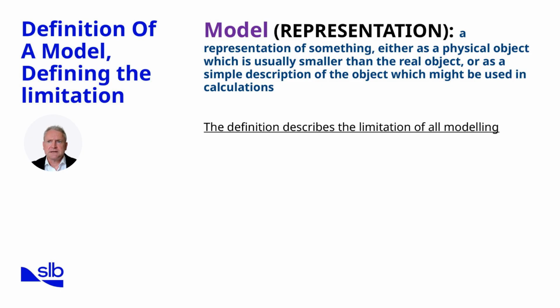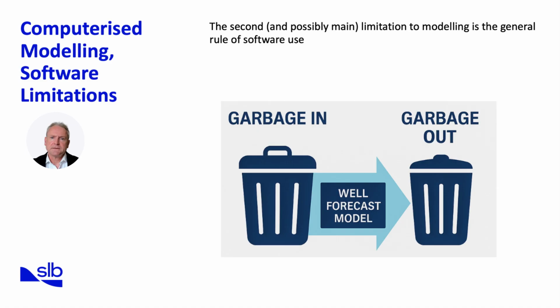This brings us naturally to the next topic, the additional limitations imposed by computerized modeling and the software tools we use every day. Computerized modeling is the standard in drilling today, but it introduces its own set of limitations. Software programs are powerful, but they are only as good as the inputs provided and the assumptions built into their algorithms. A common saying is, garbage in, garbage out. If the input data is poor, whether it's incomplete offset data, incorrect fluid properties, or misinterpreted formation pressures, the software will still generate results, but those results will be misleading.